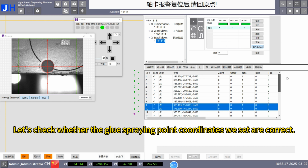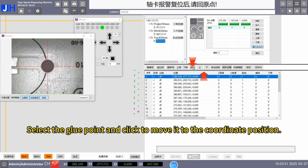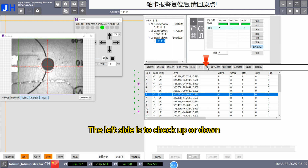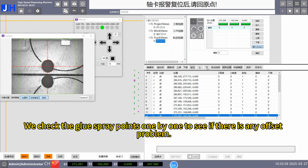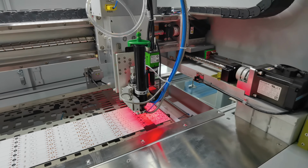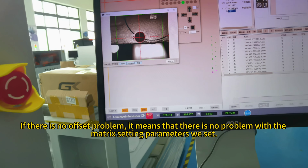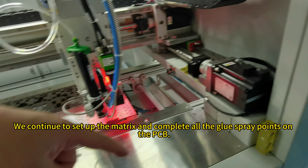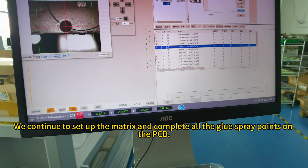Let's check whether the glue spraying point coordinates we set are correct. Select the glue point and click to move it to the coordinate position. The left side is to check up or down. We check the glue spray points one by one to see if there is any offset problem. If there is no offset problem, it means that there is no problem with the matrix setting parameters we set. We continue to set up the matrix and complete all the glue spray points on the PCB.